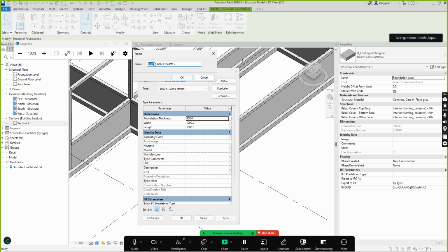This decision is made by somebody who understands structures, somebody who understands construction. So Mr. Nee, since you are on the site, what is the advisable size for the foundation pad? If it's a single story, yes sir, 600 by 600.